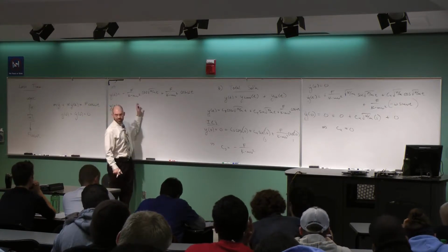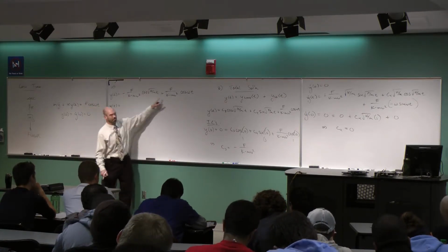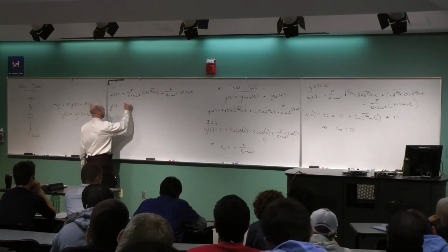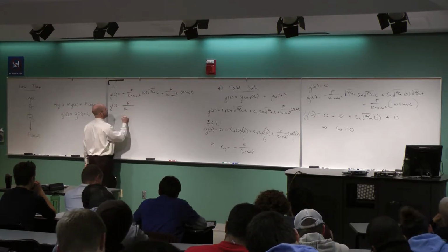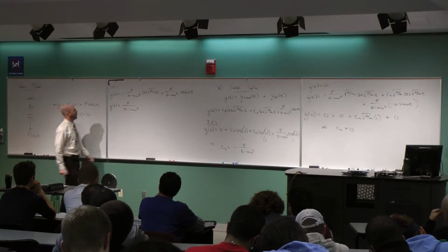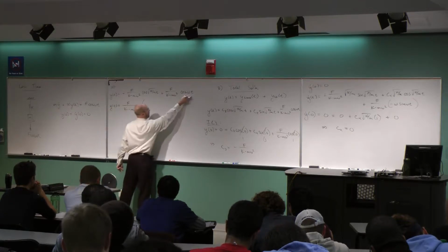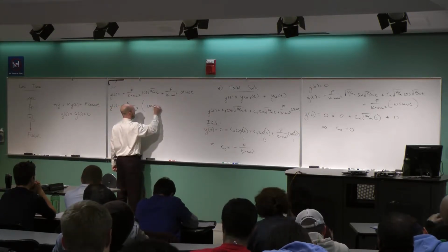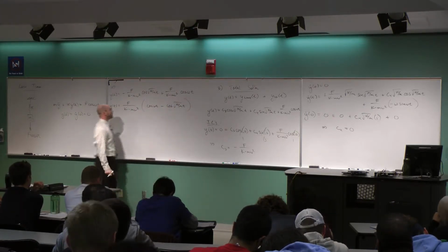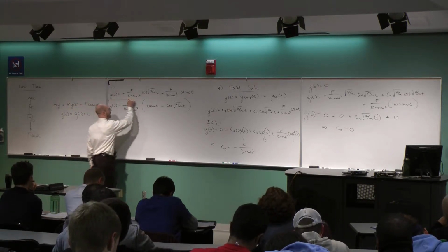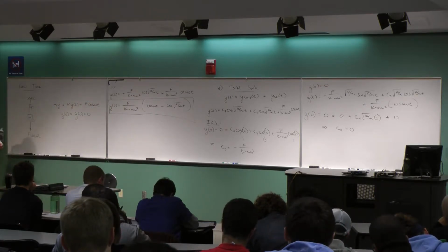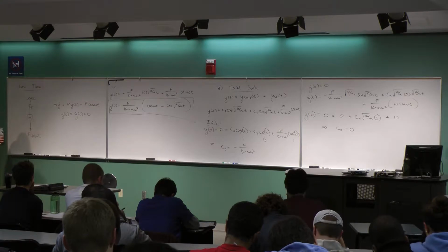Yeah, I've got the same constant in front, and then this is a negative and this is a positive, so I could flip the order of those two and write it as a subtraction. The most elegant way to write this, I think, would be to factor out this amplitude-looking function, f divided by k minus m omega squared, and multiply that by one minus that: cosine omega t minus the cosine of root k over m t. This is what would have a box around it as the final solution that satisfies the governing equation and satisfies the initial conditions.